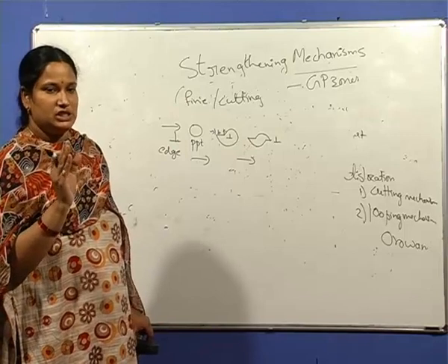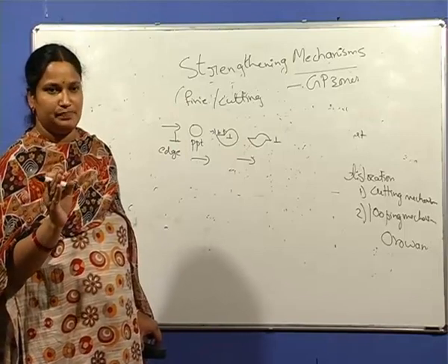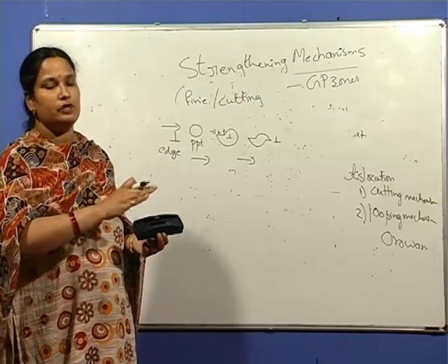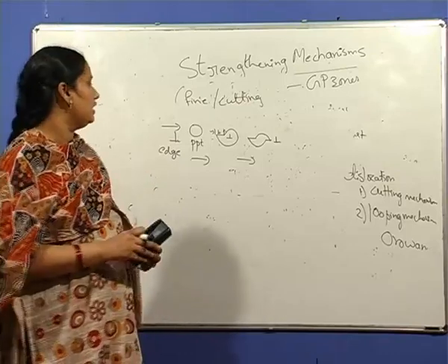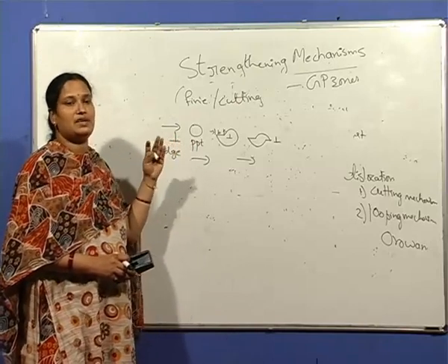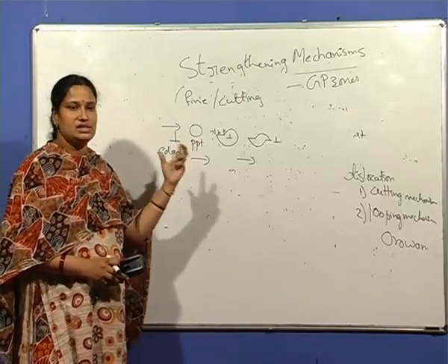The passage of the dislocation occurs by the cutting mechanism because these precipitates are shearable. They can be easily deformed or easily cut by the moving dislocations, which is not easy; it requires very high stress. So that is the strengthening mechanism.